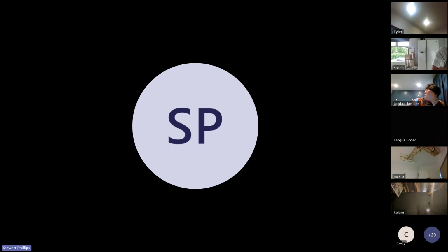One example, if we were decommissioning one switchboard inside of the Wakefield Hospital facility and then recommissioning a new one. Because it was feeding certain areas of the hospital, we had to wait until the weekend when they had fewer patients and they could move them to areas we wouldn't be affecting. So then we had to decommission the board, just double check we hadn't accidentally turned off anything that wasn't supposed to be turned off, and then recommission it afterwards. This was at stage one, Andy, if you're wondering, not stage two.